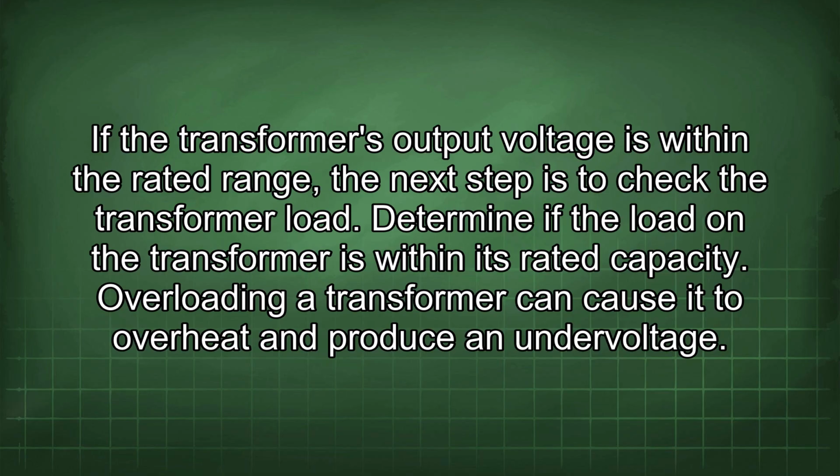If the transformer's output voltage is within the rated range, the next step is to check the transformer load. Determine if the load on the transformer is within its rated capacity. Overloading a transformer can cause it to overheat and produce an undervoltage.